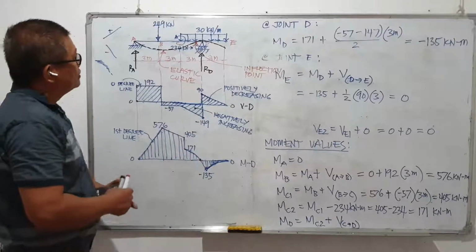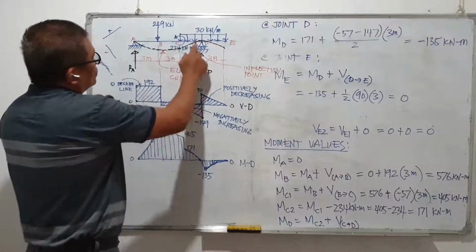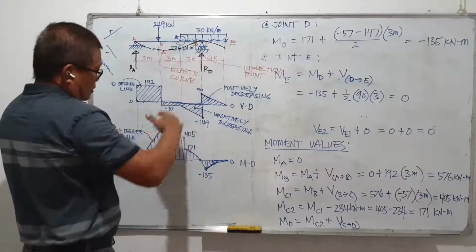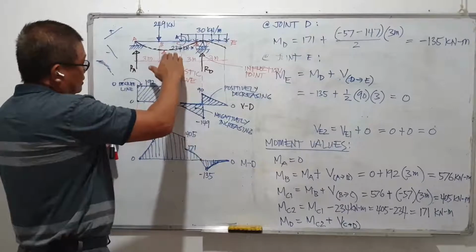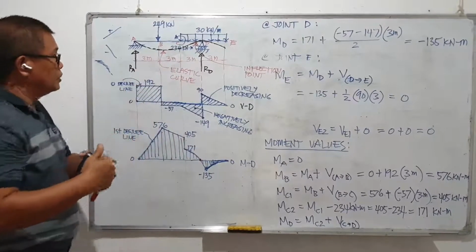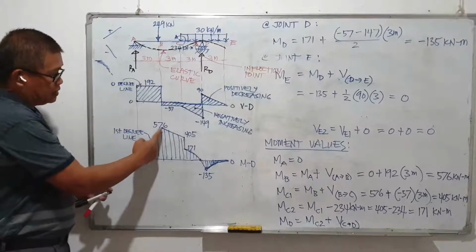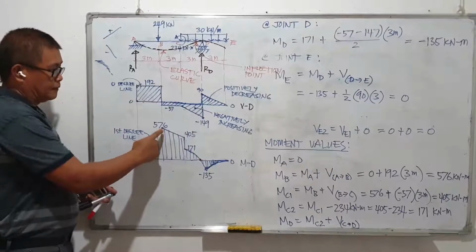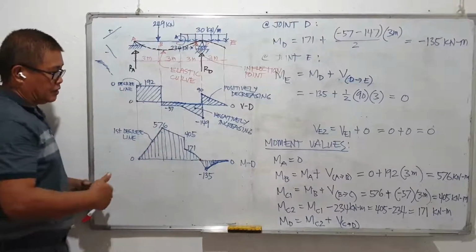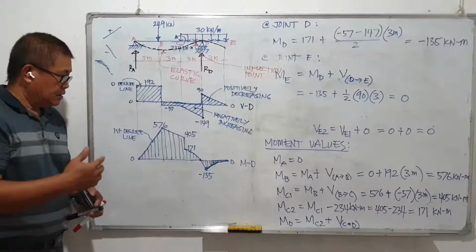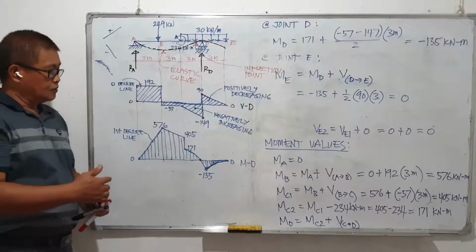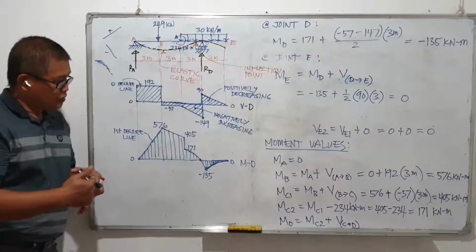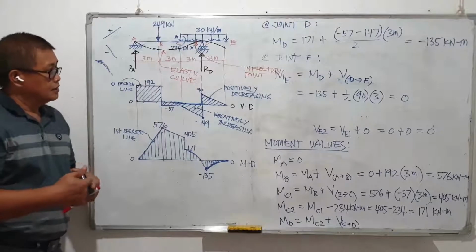Otherwise, we have to arrange our reinforcement so that the splicing will not fall especially at the location of the maximum moment, because it is experiencing the largest stress. So we should not place our splices at this position.